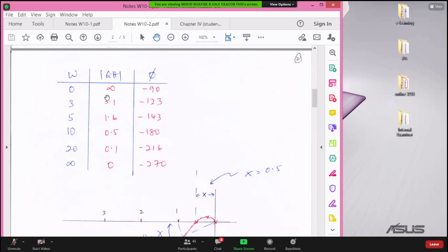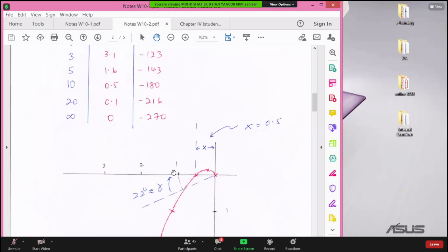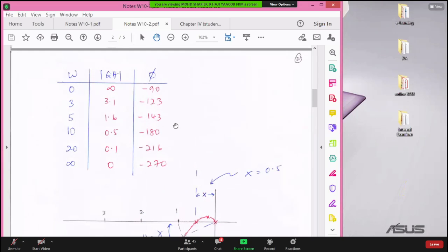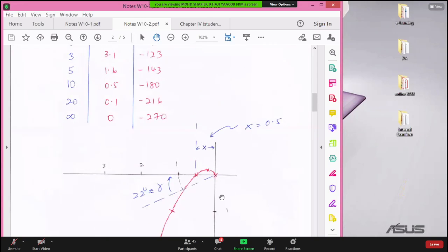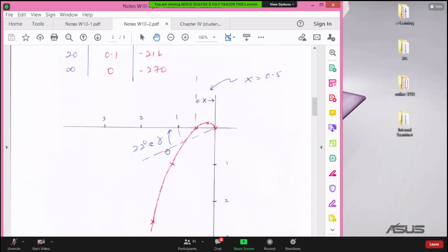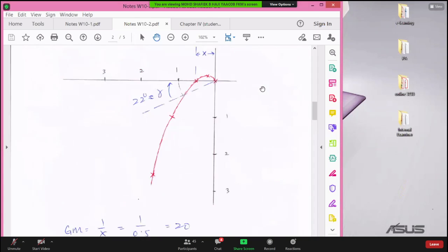So you can see that the biggest magnitude is 3. So now if you look at my scale here, there's one, then it should be -1, -3. So this is the real axis, this is the imaginary axis. Now you can transfer the point. If the question asks you for your phase margin and gain margin, you can now see the phase margin is around 22 degrees and the gain margin is about 0.5, which is equal to 2.